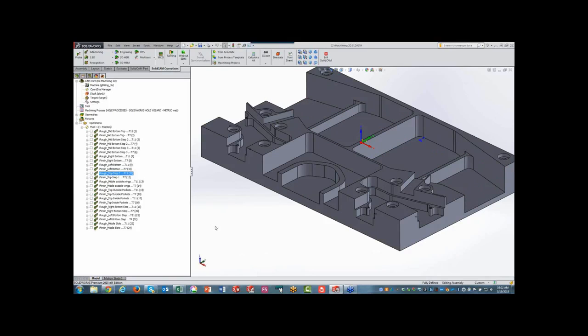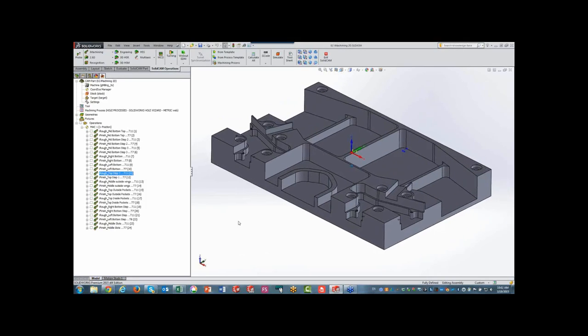So again, I want to emphasize the programming time over here as far as creating all your operations can take just about the same amount of time as doing it in 2.5D. A roughing operation for this area and that area as well. This pocket over here, all of these were done exactly the way I did it in 2.5D. Not to mention that I still have to do also the drilling operation, but we'll talk about that a little later.